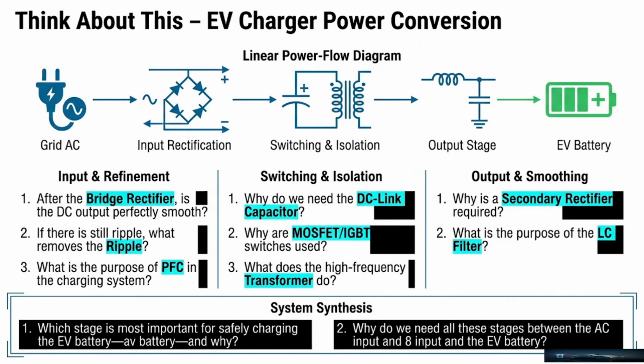We will discuss in detail the rectification, the diode, the bridge rectifier, its application. We will take the positive half cycle, follow the current through the 4 diodes and then take the negative half cycle and see what changes.